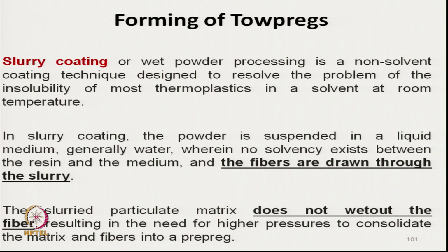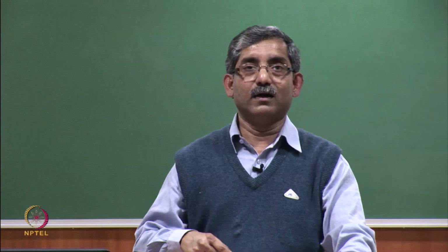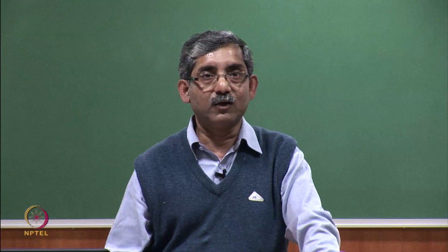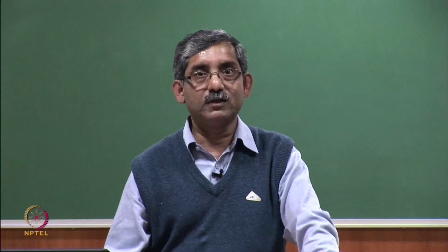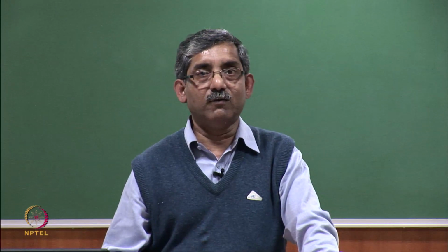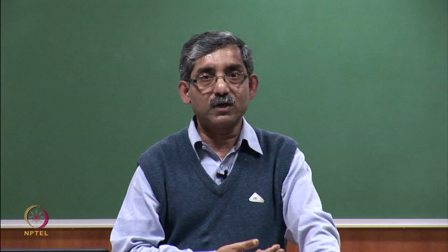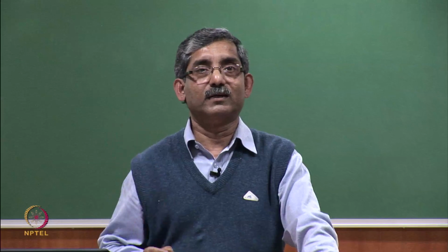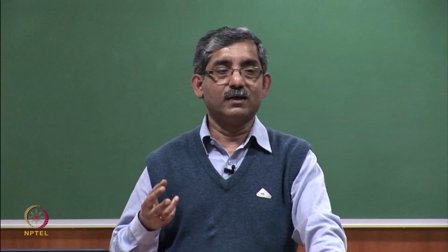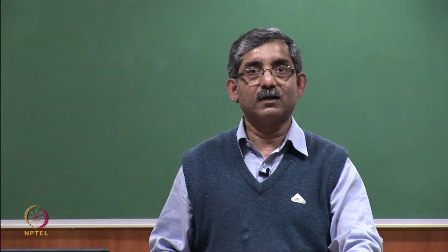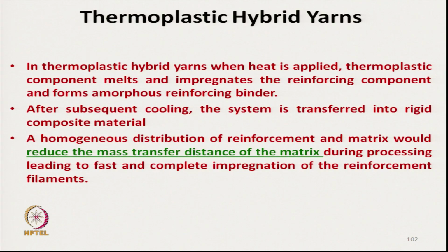The powder of the thermoplastic material is formed into a suspension in the liquid, a powder suspension in slurry form, and the tows are drawn through that slurry, and the thermoplastic materials are deposited on the surface.